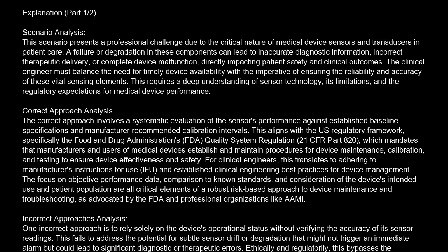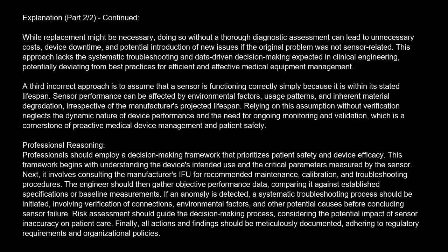Another incorrect approach is to immediately replace the sensor based on a single, uncorroborated anomaly. A replacement might be necessary. Doing so without a thorough diagnostic assessment can lead to unnecessary costs, device downtime, and potential introduction of new issues if the original problem was not sensor-related. This approach lacks the systematic troubleshooting and data-driven decision-making expected in clinical engineering, potentially deviating from best practices for efficient and effective medical equipment management.